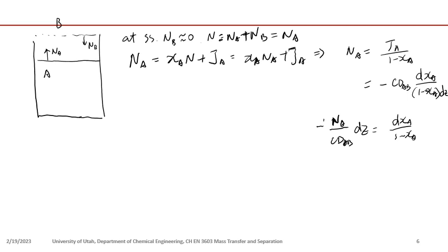So we need to hurry up. Then we talk about Fick's law, right? Which is a model we use to solve for diffusive flux, in which the mole fraction gradient or the concentration gradient is the driving force for diffusion, and the diffusivity is like the inverse of the resistance for mass transfer, right? If you have a high diffusivity, then your diffusion is fast. That means the resistance for diffusion is low, right? And we apply Fick's law to solve for the two bulbs problem and the baker's problem, right? Well, that's in the lecture notes.